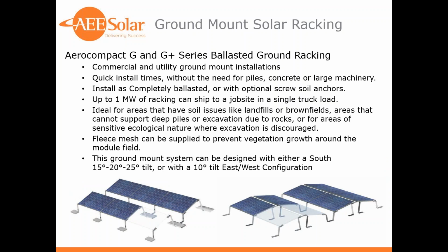So we also have an offering from Aero Compact. This is an alternative to the penetrating system, but they have a ballasted racking system for the ground. We're really seeing this take off. Very quick install times. No need to dig holes and set piles for concrete. No large machinery needed. No pile driving. No engineering study needed for soil. No frost heave. Special considerations if you have a frost line where you're trying to achieve a depth.